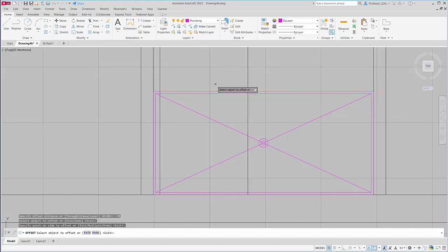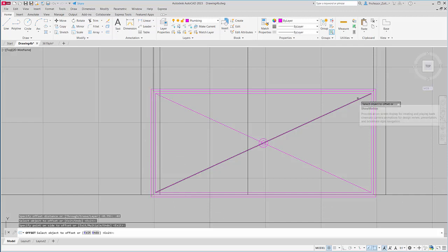There we go. Again, I'm using the wall layer drawing as the actual components of what I'm going to offset and trim. And from here, I'm going to offset the thickness of the door, which is the equivalent of the wall thickness of 0.02. So I'm going to offset that. And again, a lot of this stuff is symbolic. Now look at how big that is. So I'm going to trim it.